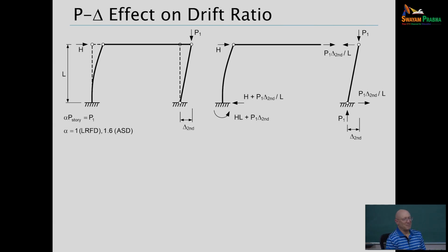Well, in ASCE 7, we have 1.4 times dead load. Divide that by 1.5, and you've got a load factor less than 1. So some engineers look at that and worry. Oh, and you've got a resistance factor on the other side. It's okay. And then 1.2 dead plus 1.6 live, divide that. The engineers that prefer ASD want to see dead plus live. That's our load combination, dead plus live.